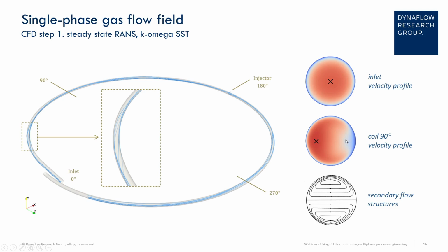So you get a secondary flow from the point of high pressure to the point of low pressure. This is quite common for flows in circular patterns, which means that in the cross section you actually have distinct cells, a secondary flow of distinct cells. This movement can be considered beneficial for mixing if powder particles are small enough to be regarded as tracers. The trajectory of larger particles is strongly determined by inertia.